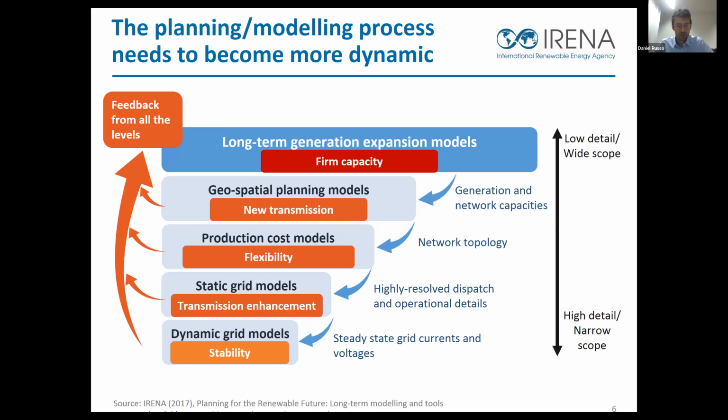And this whole process, when you introduce variable renewable energy like wind and solar, has to change in many different ways. And a lot of that has to do with the unique impacts that Jenny was talking about. In the long term, you need to start thinking, if my solar is producing at high levels, what happens at night? Do I need to add additional capacities, what we call firm capacity, to make sure demand can be met with supply at all times?